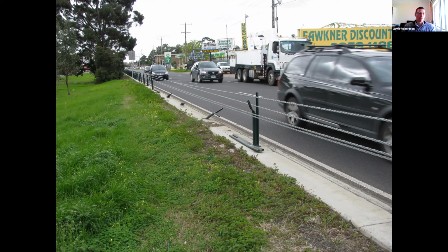If we do have 3 or more lanes, however, we should be looking to provide the same offsets, 3 to 4 metres, on the median side as well. The VicRoads Road Design Notes to do with continuous barriers and narrow flush medians with central barriers provide guidance on offsets to barriers in those situations. So I encourage you to look to those as well for some more guidance.